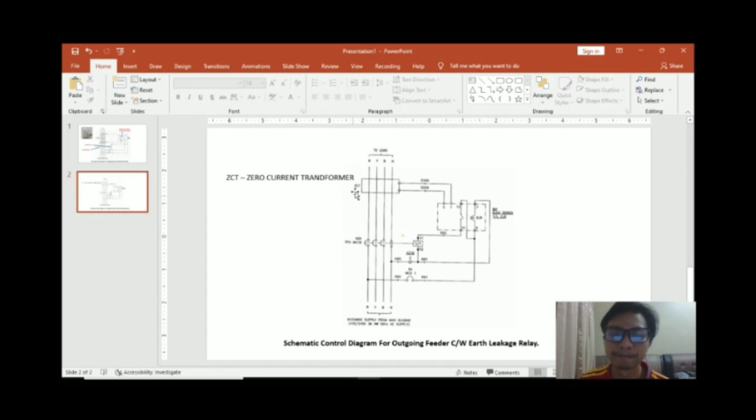So it clamps, and this is a connection cable. You tap in 1 and 2, and then you tap in 12, which is normally open, and tap in 10 connects to the ST shunt trip coil. The shunt trip coil connects to the circuit breaker MCCB.